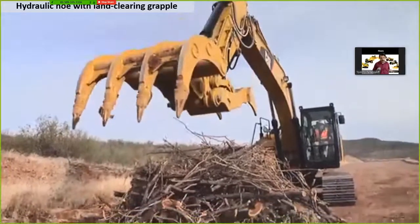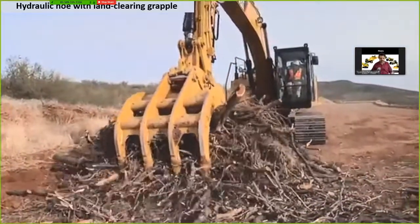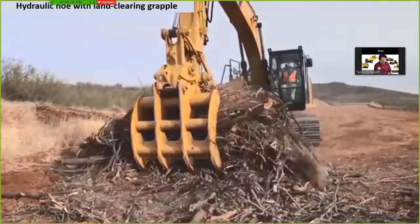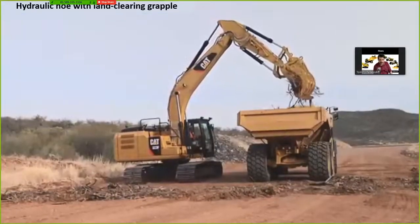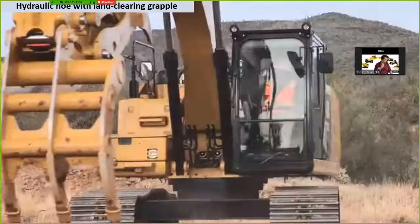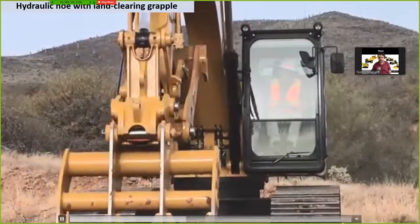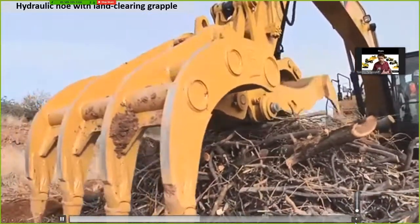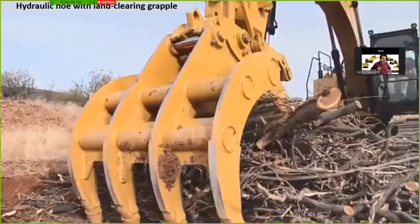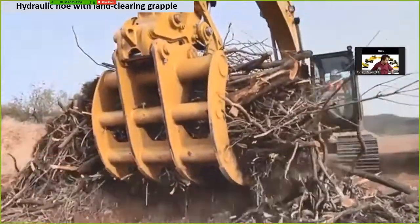So if you want to select a hoe, there are different factors you would take into consideration. One is the maximum excavation depth of a hoe. Second one is maximum working radius. So do you need to cover a large area or a smaller area? The radius of the area would impact the choice of the hoe.